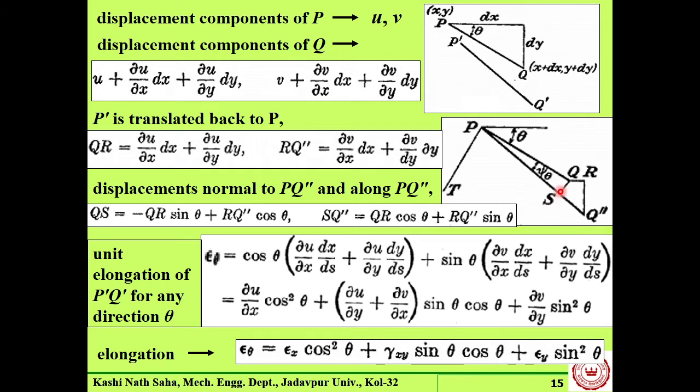If this is parallel shifting, then the angle between PQ and P prime Q prime is coming as this angle psi, say. Okay. And this particular angle psi is a function of initial configuration of this line PQ. That is given by this angle theta. Right? We could have selected another line PQ at a different half of this theta, 2/3 of this theta. Anything was possible. So this psi is a function of this angle theta, so psi suffix theta.